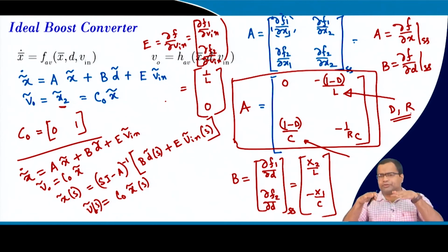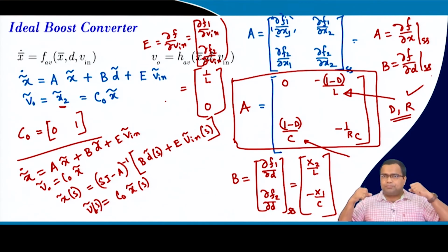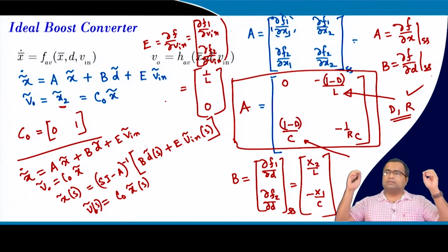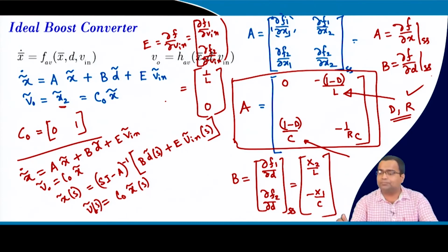This is the operating point, that means the duty ratio will vary based on your input-output voltage relationship. Even for a practical converter, we saw that if there is a load transient, R will definitely vary, and in addition to that, there will be variation of duty ratio, because the practical duty ratio will be slightly different from ideal. So, in order to anticipate that additional drop due to the finite DC output impedance, you need to increase it. Suppose there is a load step-up transient, your effective duty ratio has to be slightly higher than the ideal duty ratio to get the desired output voltage. So, that means duty ratio will also vary with the load current as well.